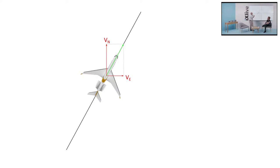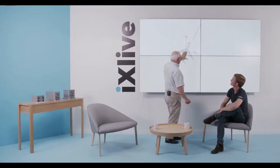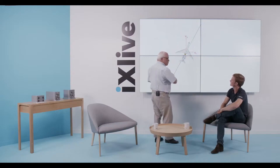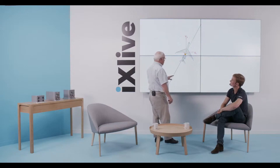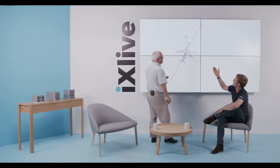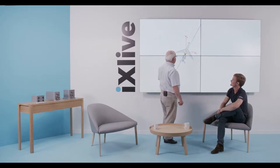With no specific error. But imagine that the aircraft, there is some wind, and so the aircraft is facing a heading which is different from the course. So the trajectory of the aircraft remains the same. It follows the straight line. The velocity remains the same, and the measurements of the GNSS will be exactly the same as in the previous drawing. 3D velocity will remain the same, and the trajectory as well. But the aircraft is not facing the same heading.